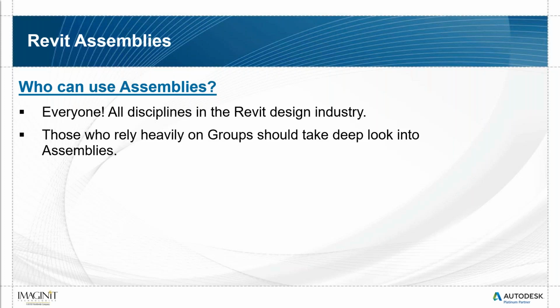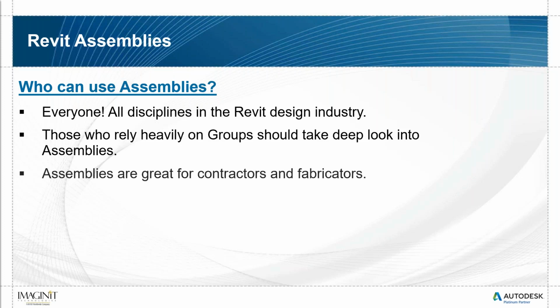So if you zoom extents on their 3D views, they have all these groups sitting outside. That's okay, but you have to worry about cropping those items out of the project, and they heavily slow down your project if you need to manipulate them. So assemblies may be a tool you want to look at because you won't have to create those objects outside the project in order to view them.